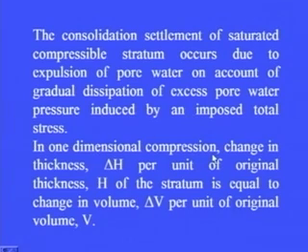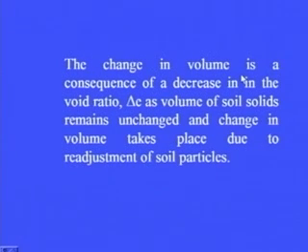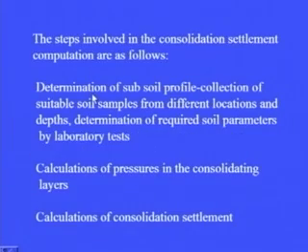In one dimensional compression, the change in thickness delta H per unit of original thickness H of the stratum is equal to the change in volume delta V per unit of the original volume V, and this change in volume is a consequence of a decrease in the void ratio delta e, as volume of the soil solids remains unchanged and the change in volume takes place due to readjustment of the soil particles. Volume of solids will remain as it is. So, using this concept, we can determine the settlement.